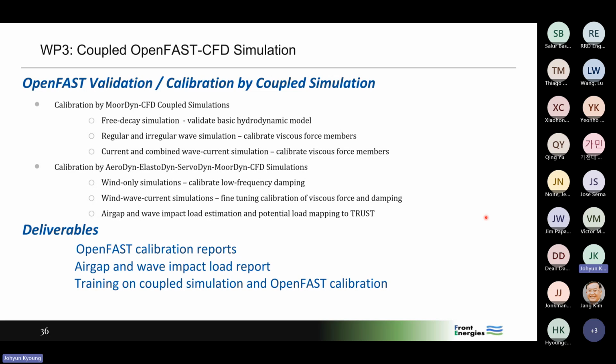So what FE wave allows you to do is combine that CFD solution near the body with the potential flow far from the body. That's not a feature you can get directly in Star-CCM+, but that's what FE wave provides: that extension to near-body CFD, far-body potential flow. Correct me if I'm wrong, but that's my understanding. Yes, you nailed it. Okay.